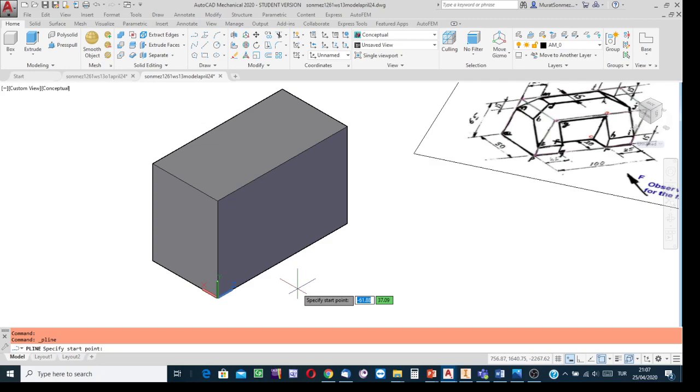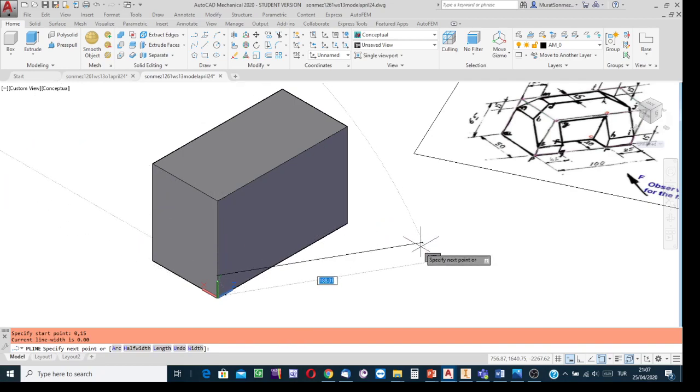Yes, the abscissa value is 0. Click on the comma key. Ordinate value, you know, where is the y-axis? The y-axis is over here, pointing up. Since the y-axis is in the up direction and my purpose is to mark the point relative to the origin at a higher level, the ordinate value must be written as positive 15. Press enter. Yes, now that is the starting point.